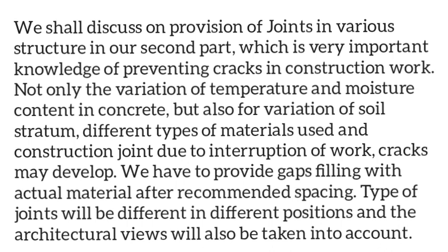Here, we got the knowledge of different types of joints preventing cracks in construction work and the filler materials to protect the architectural view. The causes of cracks are not only the variation of temperature or moisture content in concrete but also the variation of soil stratum, different types of material used, or interruption of work. We shall discuss the type of joint material used in different positions in our next part.